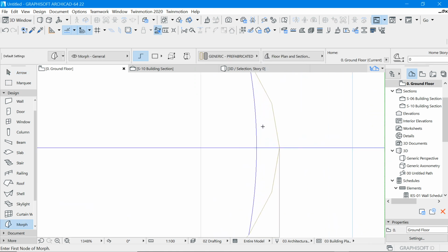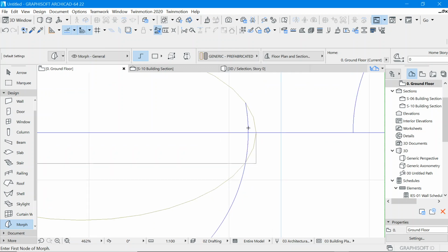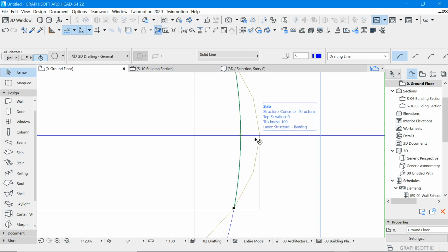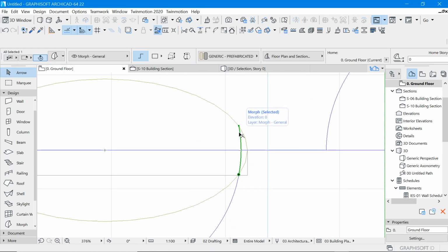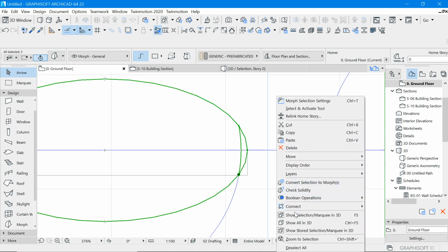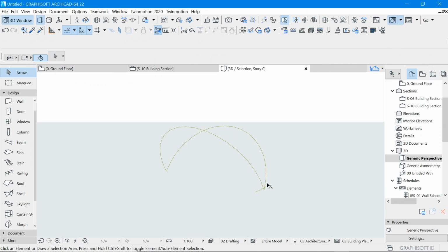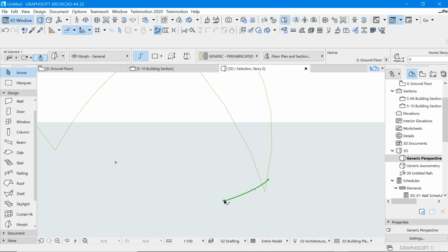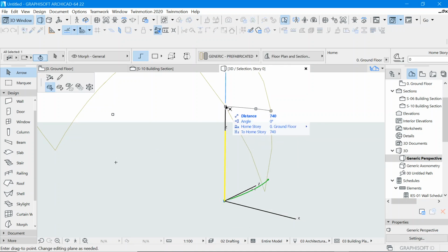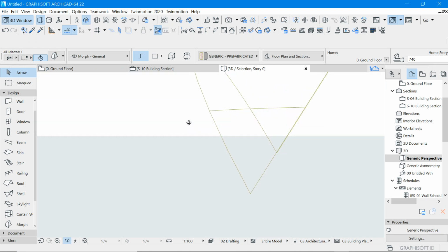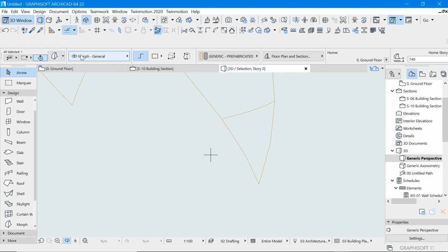properties of the Morph tool, insert them in this that you've just created, then get rid of the line or the arc, pick that portion of the segment and this in 3D, right hand click, fit in window in case it's not visible, click this, raise it up to meet that segment accordingly, and once it's like that, go back on ground,